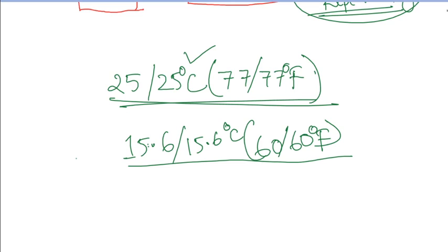As a result, your total pavement quality will be degraded, because decisions about how to place this bitumen and other aspects will be made based on this particular value, the specific gravity of these bituminous materials.